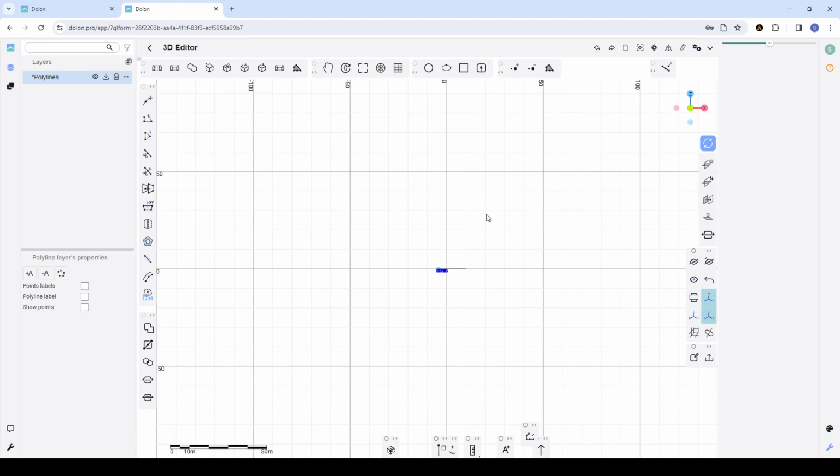So we can toggle that plane. In order to toggle the plane or make some elevation constant, we can use this toggle reference plane. To set the elevation, we just click this button. Then let's say on this level, 50. That coordinate is currently 50.